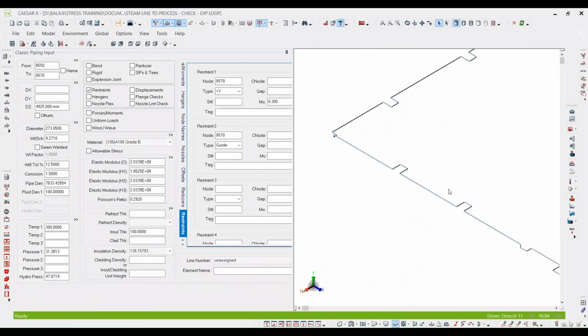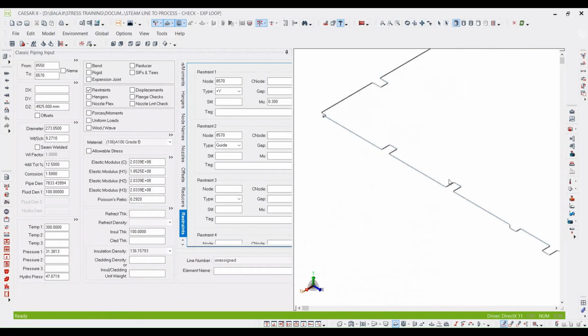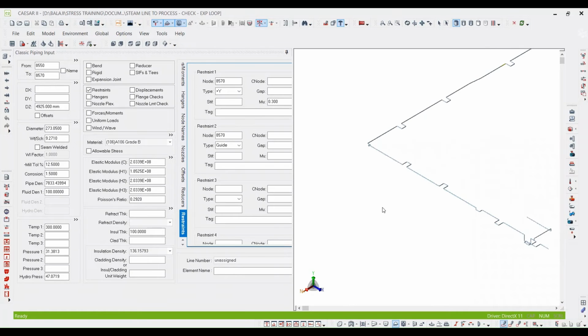So here, I think you might have understood the concept, no? First, for a straight line, you have to find the null point and introduce a limit stop, and you introduce a loop here. Once you add the loop, you have to find the null points before and after, and add limit stops. If this one loop is okay, and at the end the displacement is within 100 mm, then you can leave it like this.